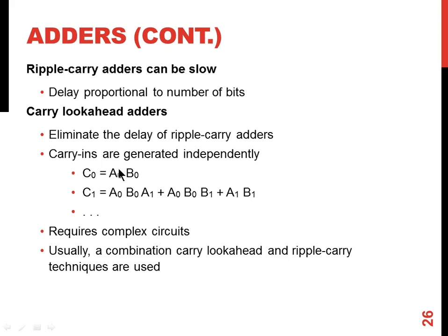But there is a negative for that. When you build these equations, you need to build them using gates. So there will be more complex circuitry involved, and overall there will be what we call a logical overhead or area overhead on the design, where we need more gates to implement the carry outputs of each stage. When you work on very big designs, normally you don't work only with ripple carry or only with carry look ahead adders. Normally there is some combination of both.